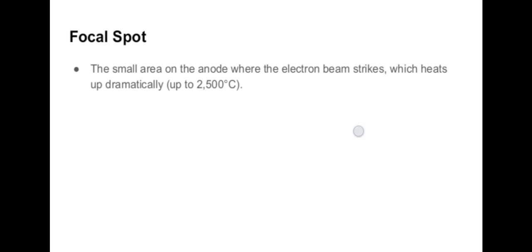Some dry lubricants such as graphite may wear off as a powder and will also destroy the vacuum. So, the commonly used lubricant is a metallic gallium alloy, which is liquid at room temperature. So, it has a low vapor pressure and good electrical and heat conduction. Some rotor models use sleeve designs in which the rotor is inserted into a hollow sleeve and the rotor has spiral grooves cut for lubricant circulation. In this, the wear and tear is very less.